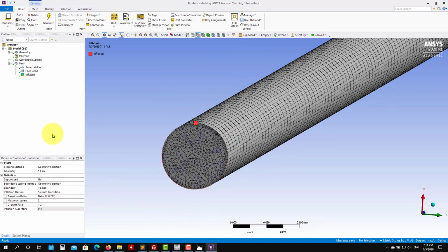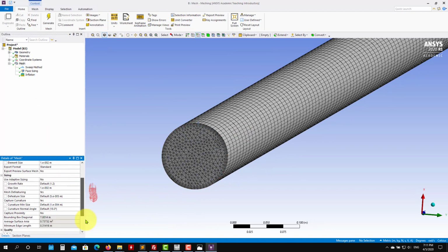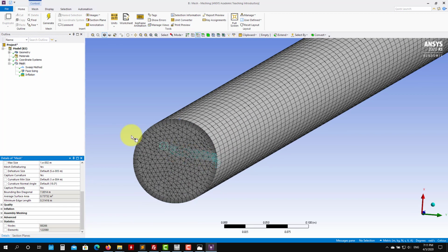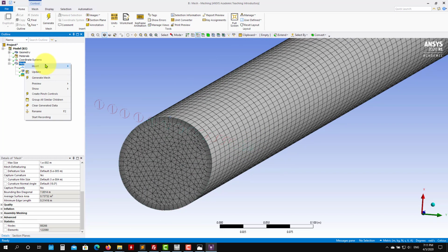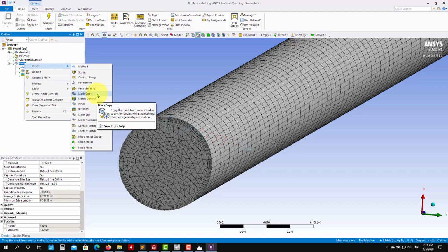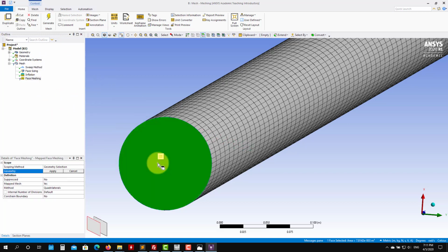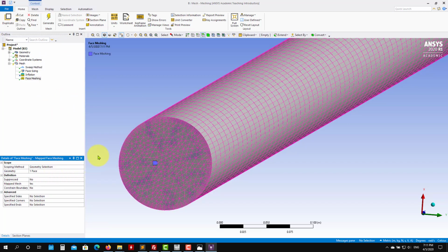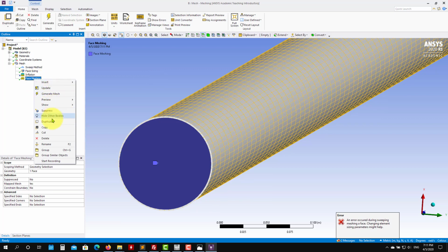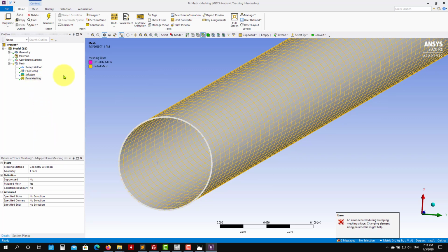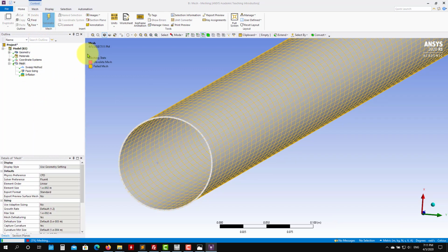and do the distribution. So let's see how many cells we have. Okay, we have this many cells, and this is cool. So you have more options. For instance, you can add face meshing. This will make a structured block topology there. Let's see what we have. Okay, now in this case we cannot use it because it will disable everything there. So you can add more refinement in the face. You can also add refinement toward the edges.